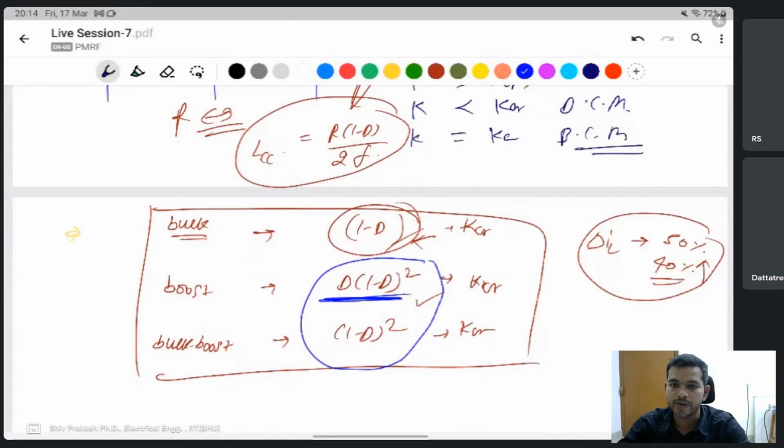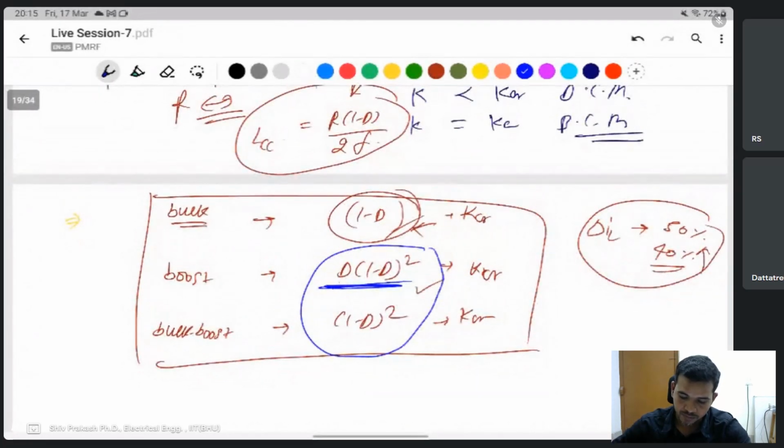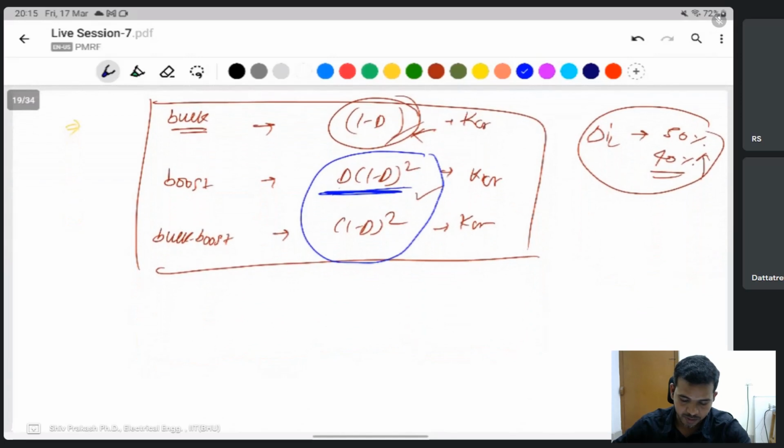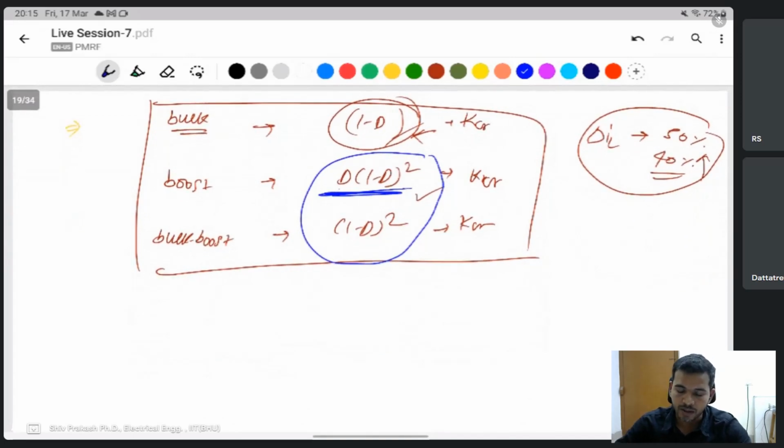This is because you use frequency control. You know about PWM frequency control, at a constant frequency or at a variable frequency. In the latest ones, variable frequency control is coming into the market, and every researcher works on this. If a converter has a light load, in that condition the frequency will be increased. If the frequency increases, it goes into continuous conduction mode. That means the control law of that PWM is AM plus FM. Nowadays they are coming like that; previously it was always fixed frequency control.